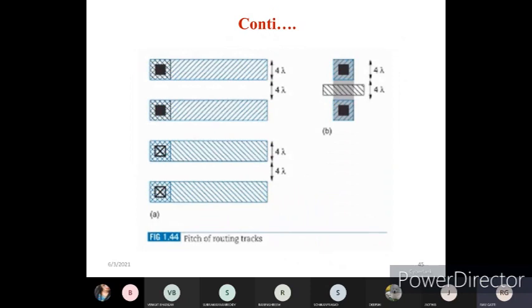And this is the contact cuts we are going to use. If you want routing of information, meaning the information has to be transmitted from one entity to another entity in VLSI technology, then you need to have routing paths. So the routing paths we are going to define, or make, in VLSI technology with these lambda based design rules.